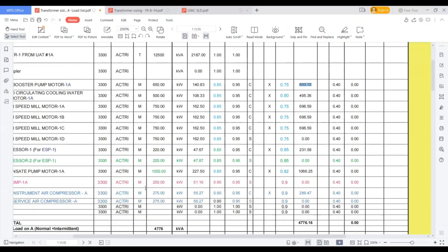Similarly, you can see the loads. You can see the pumps. There is 9. This is based on the diversity factor also. I know the operation of this, that's why I'm calling that a load factor. If I don't know, suppose for the lighting loads, I will take a diversity factor of 0.9, guys. That is the other case.